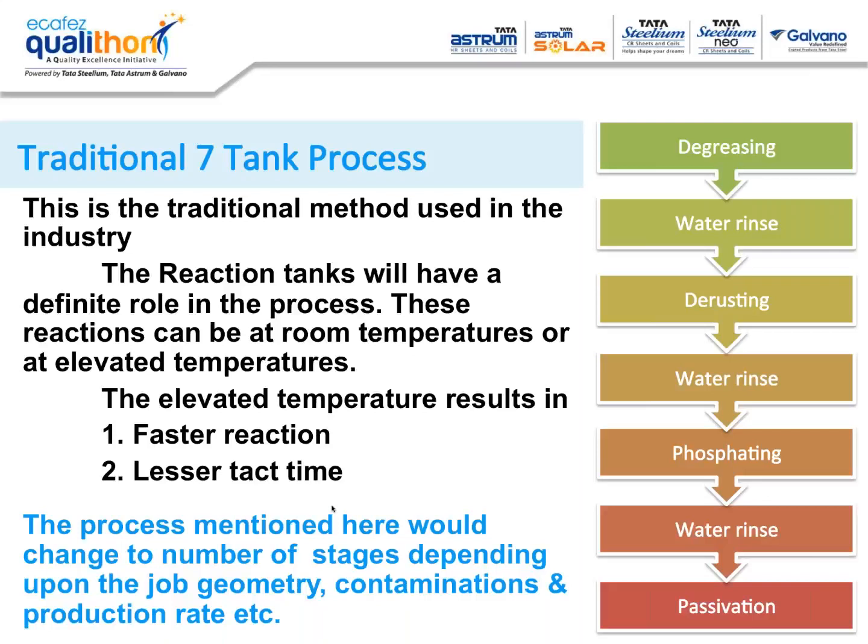So having such a big gap and having the same timings for the reactions is difficult. If you set your line in summers, it is going to need more time in winters for the reactions. So better you elevate the crucial reaction temperatures by a few degrees above your maximum ambient temperature in summers. That is the basic idea why to go for hot tanks or temperature tanks.